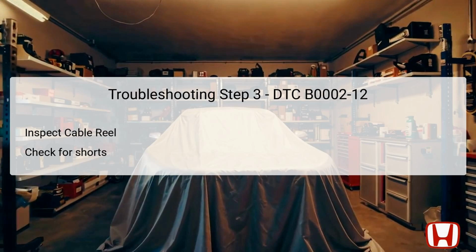troubleshooting continues. In this troubleshooting step, we need to conduct a thorough inspection of the LA2 plus and LA2 minus lines, which are crucial power supply lines in the airbag system. Before starting this inspection, ensure that the SRS unit connector is disconnected to prevent accidental deployment. With both connectors detached, the technician should check the continuity of the LA2 plus and LA2 minus lines to verify whether they are shorted.